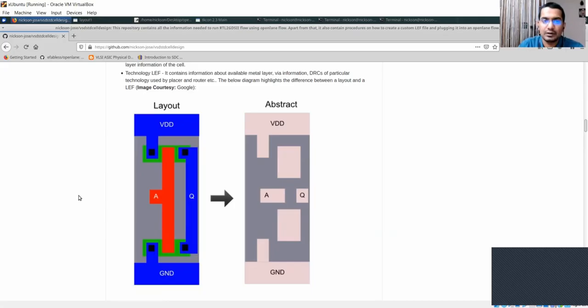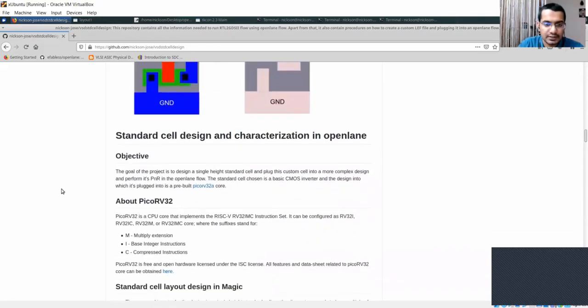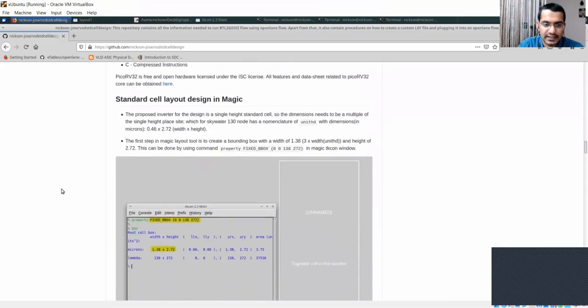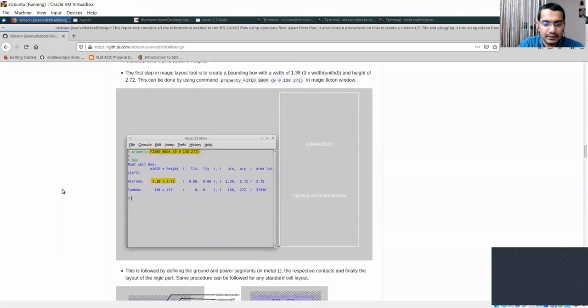If you see, the thickness of this one and this one is a bit thicker than the bottom layers, and that's exactly what happens. So if you look at the outside pins of your chip, they look much thicker in size, and this is the reason for that. As and when you go from bottom to top, the thickness of your metal layer, or thickness of your interconnects, actually increases. And once we have done that, the higher steps again remain the same.